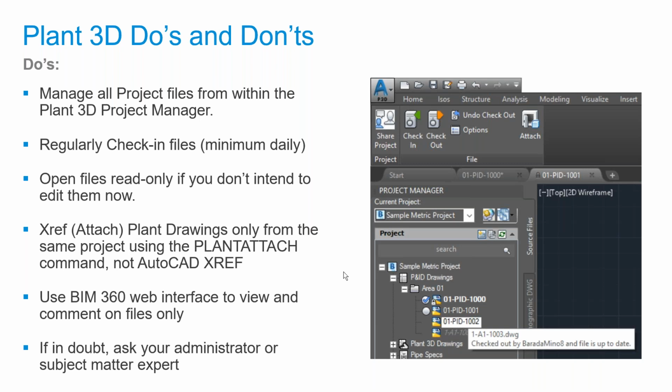But for now, if you have the drawings within the project themselves, then this XREF attach or Plant attach works pretty well. Or you can manually update the local version of that in your workspace locally, and then it will load up, but it's a manual process.